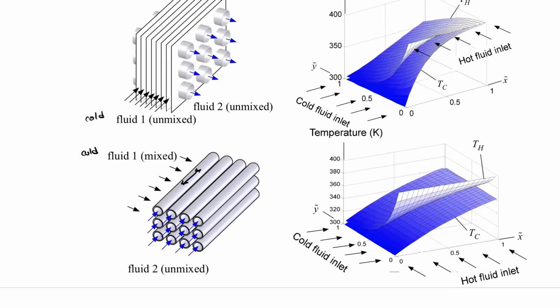Like, let's say on the outlet over here, there was some header. Yeah, like the first port on the top and a header top port. Yeah, so that is really common to do. So you come in, you have some header, it distributes over. So you'd assume by the time it gets over to the next pass that it's a mixed temperature, and every tube going in this direction is going to be coming in at a uniform mixed temperature. But as you're going through along here, it's not.